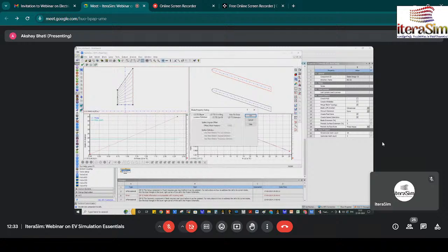And second, if you want any cutoff, meaning you want to contain any gap in hub and shroud. So here, at the leading edge and trailing edge, the gap in the hub means the lower portion on which the fan is mounted. So basically, as best practice, we want a 5% gap.